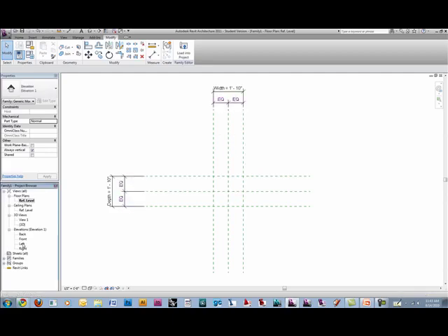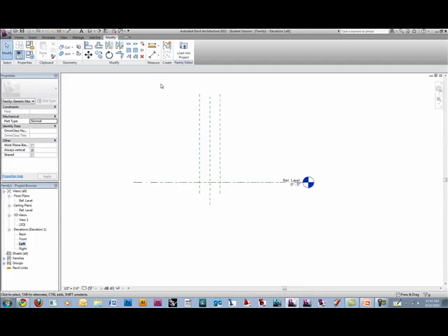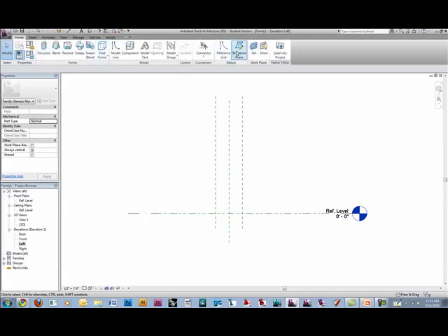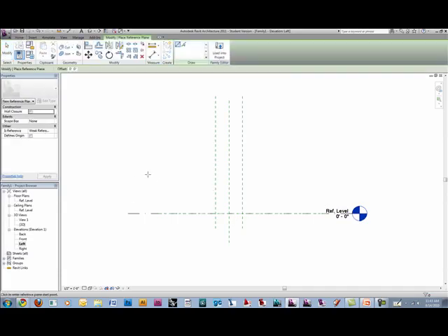But now we need to go to another view. I always use left view for some reason. It actually puts the model backwards if you use left view, but we want to draw another reference plane for the height. Doesn't matter, throw it in here.